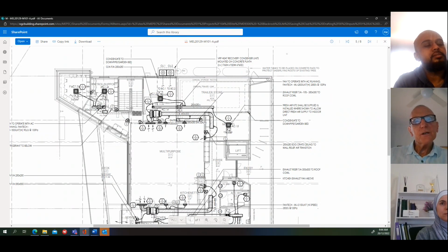It shows a duct, it gives a size. It's got cross-hatching, which indicates that it's got some sort of insulation. It may be internal insulation, but you'd have to check the legend to see what that is. And it's giving outlet locations and air quantities, and shows the design in basic detail.